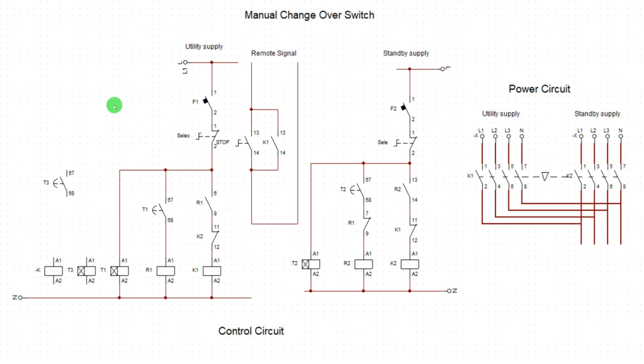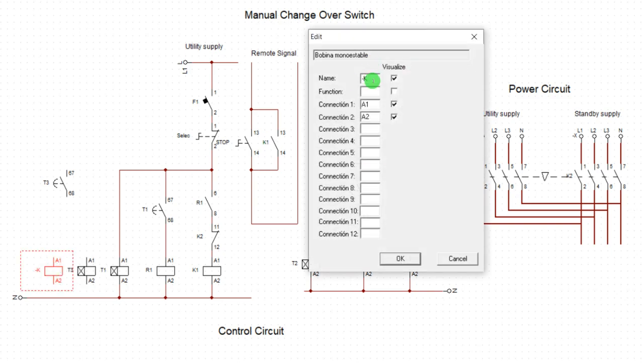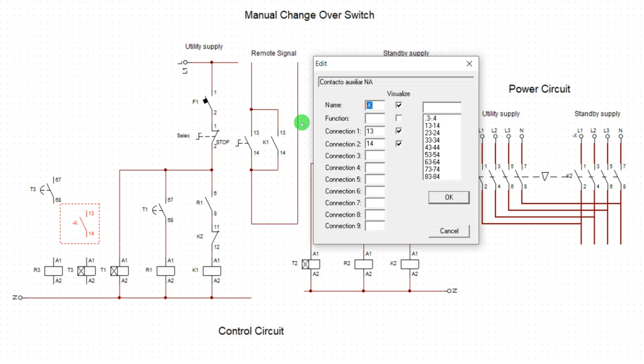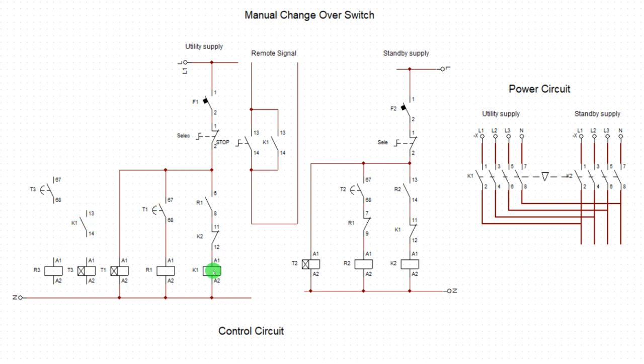All right, now let's do that together. We're going to incorporate this relay and this mechanical relay, arrow 3. Now, this is the contact to activate this relay. Now, when do we activate this timer? It is when the contactor of this has taken over. So because of that, we are going to introduce a contact here that is going to be K1.